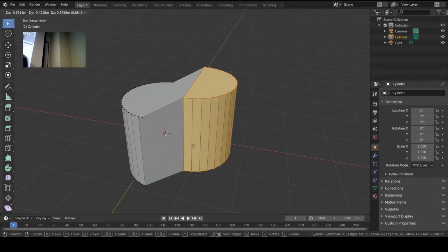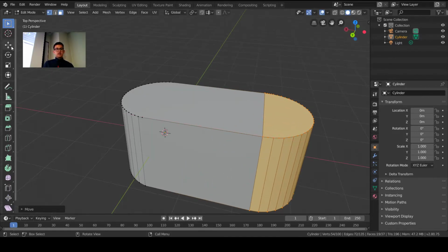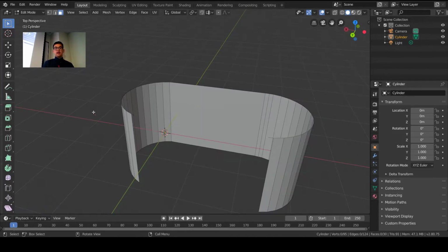If it's cut, why is it still attached? So I didn't actually detach anything yet. I just cut the faces in half. Whenever you have one object together, Blender tries to keep it together, kind of watertight, if that makes sense, so that you don't have any holes in it. But once I drag it like this, I can detach it by selecting one of these faces and pressing delete. And then now it's just kind of a C shape.